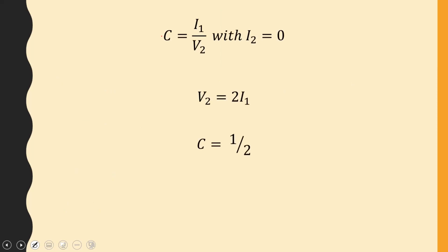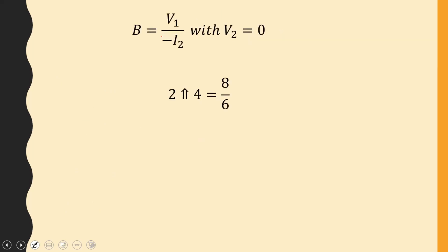All right. And then for B, again, you look back at the circuit. We have 2 in parallel with 4. Remember, the objective is to do the voltage division between the series resistor and the combination of the 2 that are in parallel.